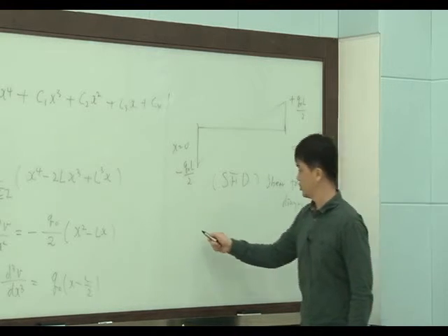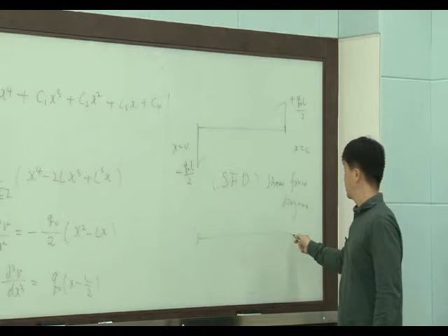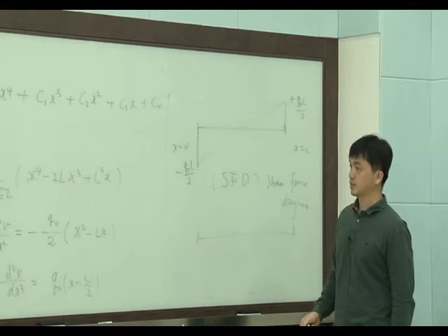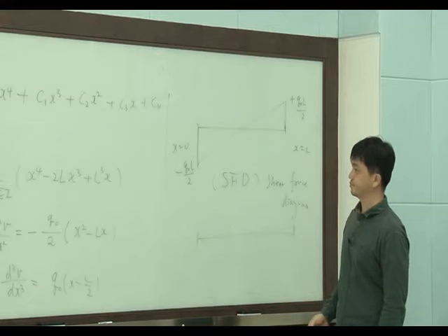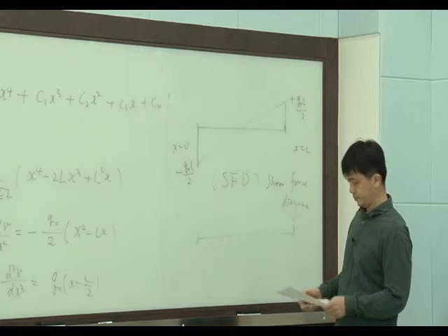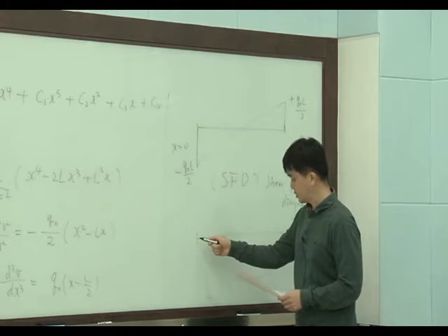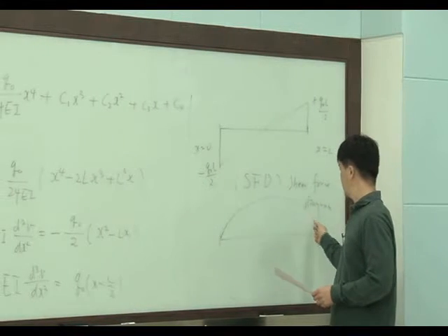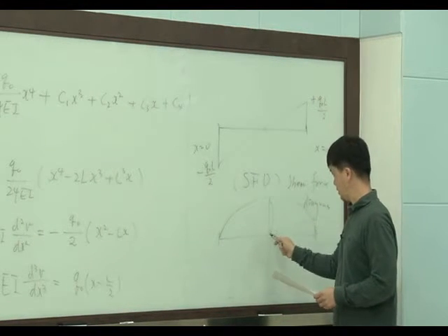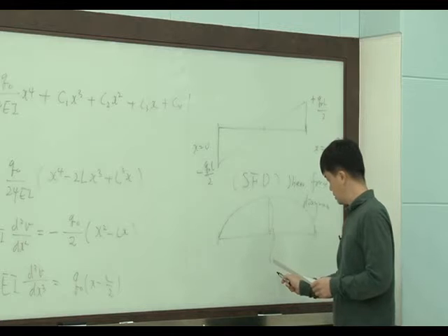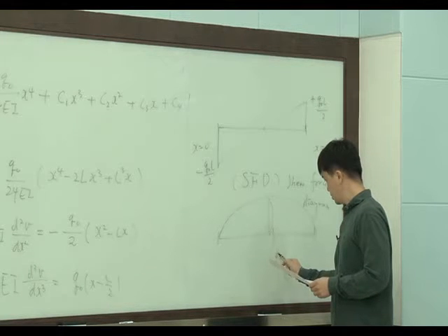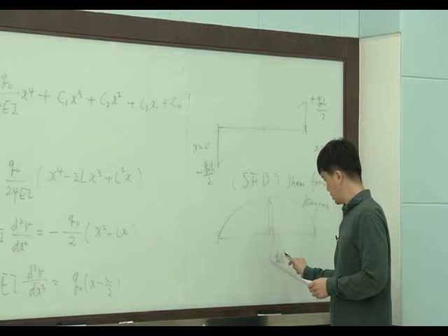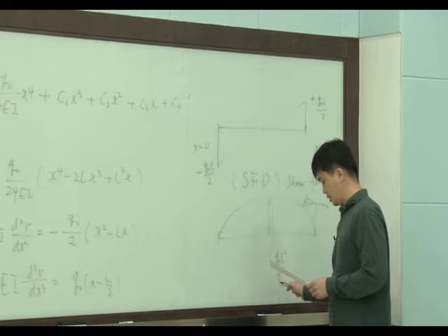And also we can have the bending moment. It looks like this, and at the center, maximum bending moment is q0L squared over 8.